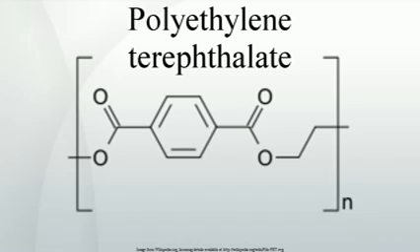PET becomes white when exposed to chloroform and also certain other chemicals such as toluene. About 60% crystallization is the upper limit for commercial products, with the exception of polyester fibers. Clear products can be produced by rapidly cooling molten polymer below Tg, the glass transition temperature, to form an amorphous solid. Like glass, amorphous PET forms when its molecules are not given enough time to arrange themselves in an orderly, crystalline fashion as the melt is cooled.